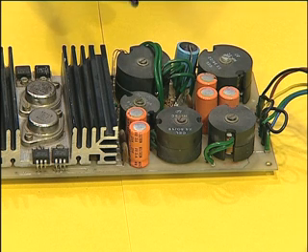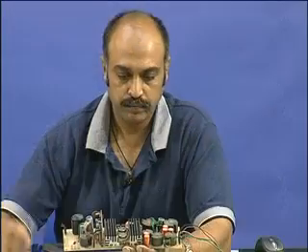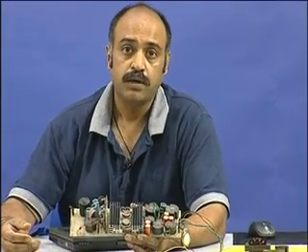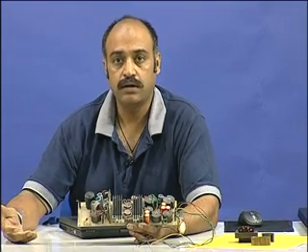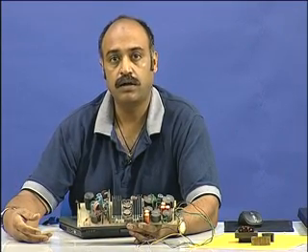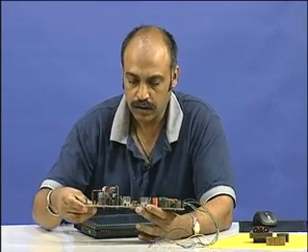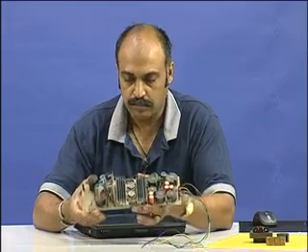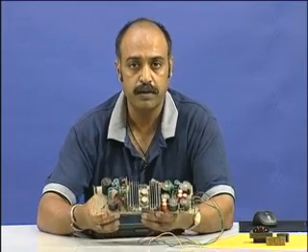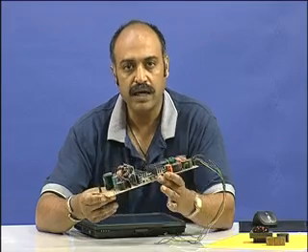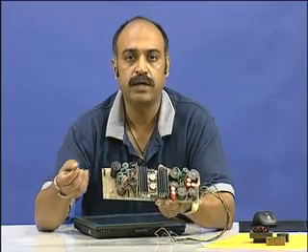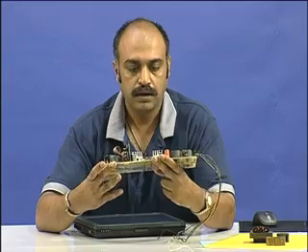Mu metal type of material can also be used for intermediate frequency range applications like 400 hertz to 1500 hertz and such. These pot cores can be used right from 20 kilohertz to 100 kilohertz, and in fact you have special ferrite cores which can go even up to 300 kilohertz, so on and so forth. Okay. So, these components arranged on the printed circuit board with just the function of power supply here will give you an idea of how the physical components are mounted onto the board and used in practice.